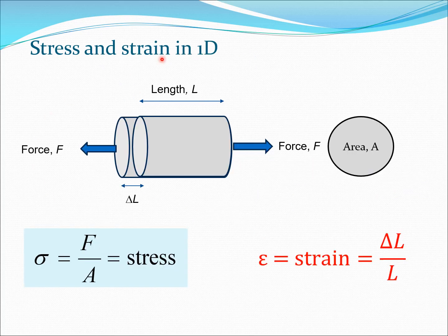Now, of course, if we recall our problem here, which we started with, the unidirectional problem or the one-dimensional problem, we saw that there was a stress, but there was also a strain. So whenever we apply a stress, for example here in this direction, what we get is a strain in this direction. So for our current problem, this would be sigma xx, and this would lead us to a strain which would be epsilon xx here. Now there would also be deformations in the different axes. So there would be a deformation in this direction and in this direction. These lateral deformations are also going to lead us to the different parts of the strain and stress vector here.